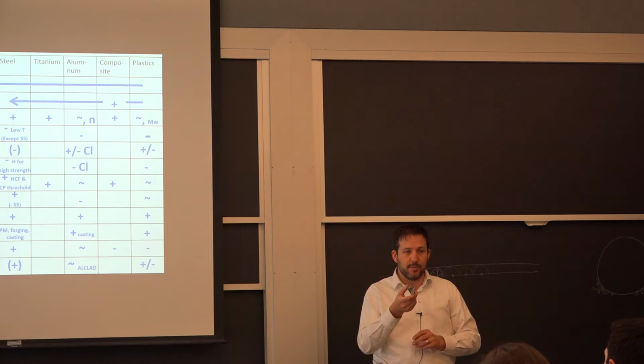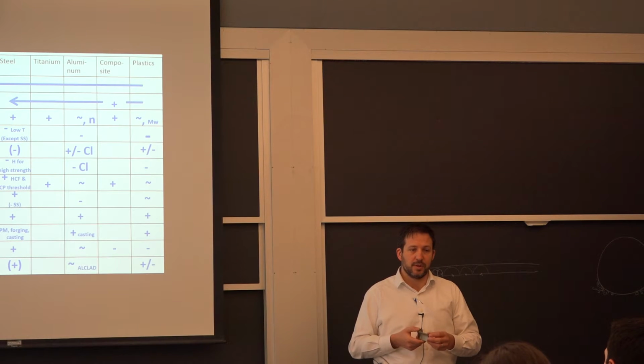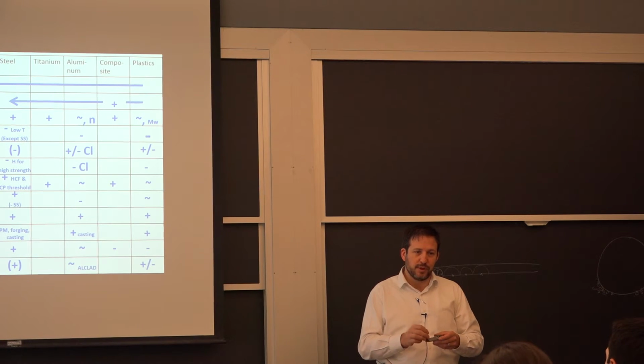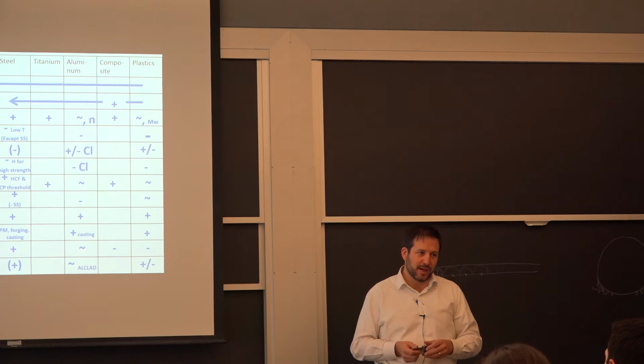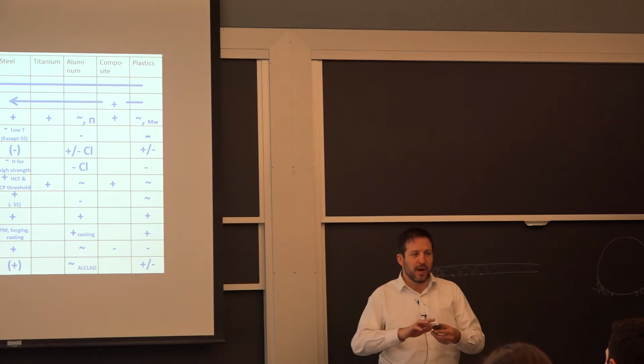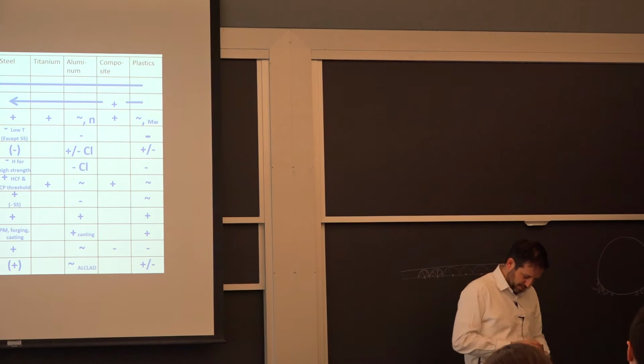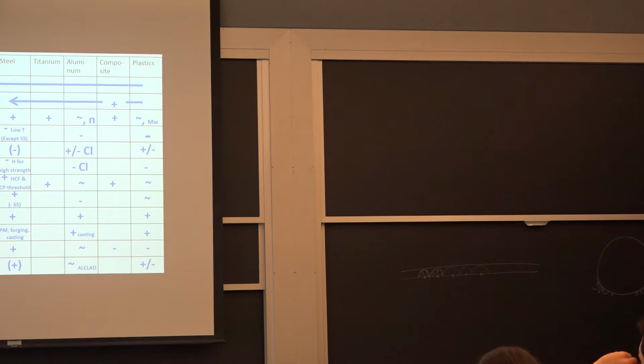This one is empty on the inside, not for weight reasons, but for circulating coolant during service. So you circulate air through this, and this one doesn't have it, but a lot of these blades will have small holes where you get the air to flow through the wall and protect the outside surface against the combustion gases. So you're creating a boundary film on the outside of the part as extra insulation for your resistance. So I'll circulate that one around as well.